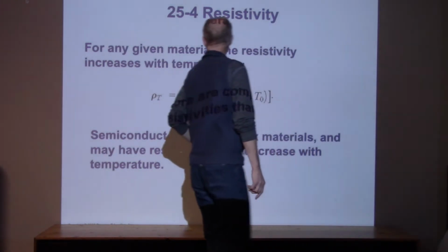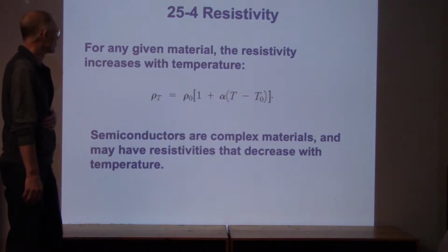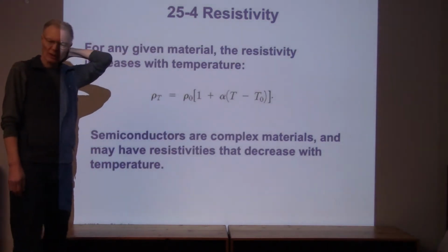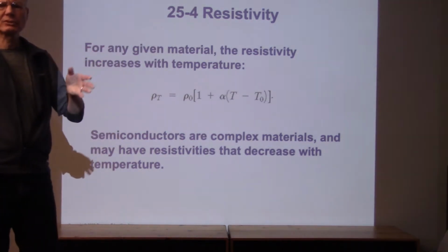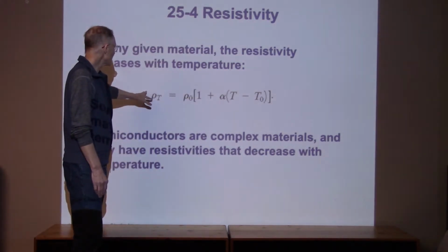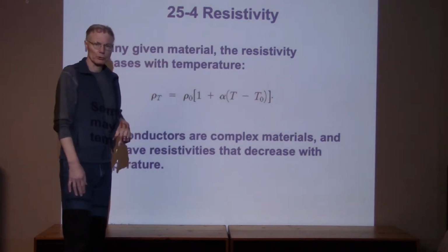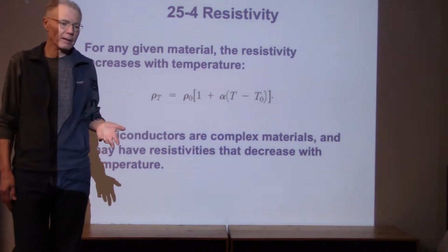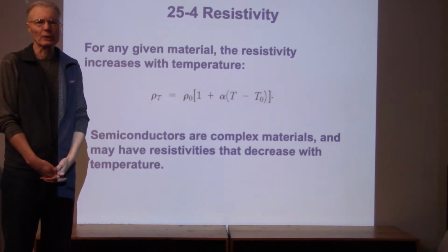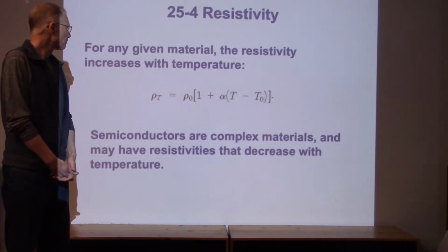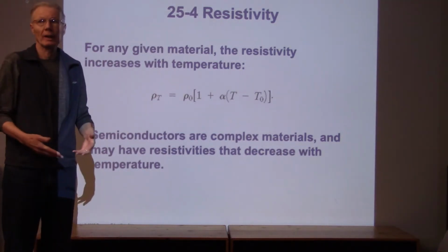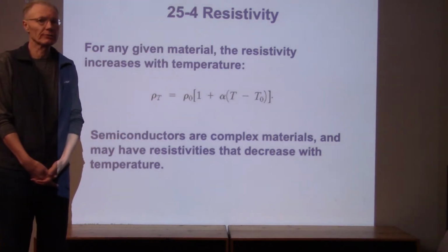All right, now there's a temperature dependence of resistivity for materials. I'm just going to refer to this formula. I think there's one homework problem. I'm not going to say much other than it's just kind of a plug-in. What you can show is that the resistivity actually goes up with temperature for the common materials. So with something like copper wiring, if the temperature goes up significantly, you'll see an increase in resistance. But at typical operating temperatures, it's going to be a small effect.